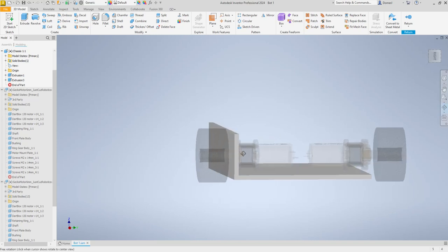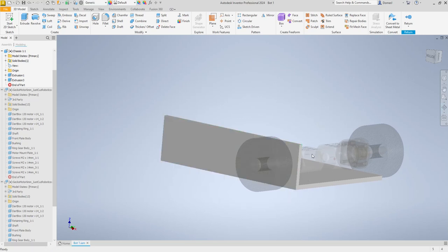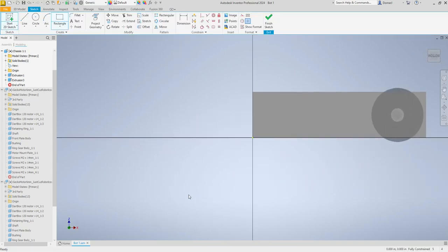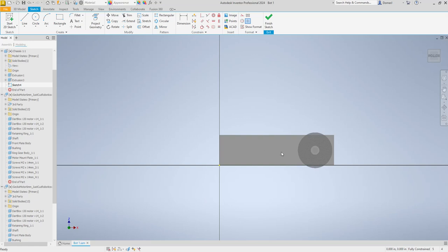Okay, here's the next advantage. Again, we have an assembly, so the motor is there. That motor has 4 bolt holes that you can bolt to the flange of the motor. We need that geometry on the sidewall. So if I sketch on the sidewall, I'm now sketching on this surface, and I go to project geometry, I can find things I want to pull forward. I'm kind of taking a guess as to which holes I need right now, because there's a lot of holes right there.